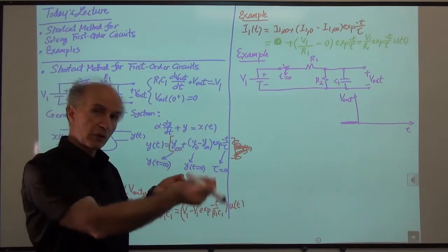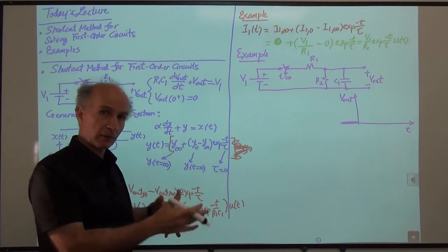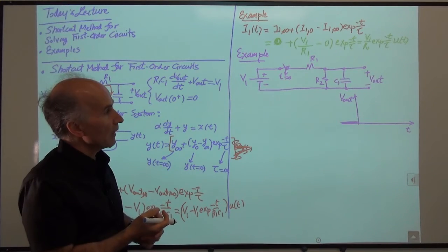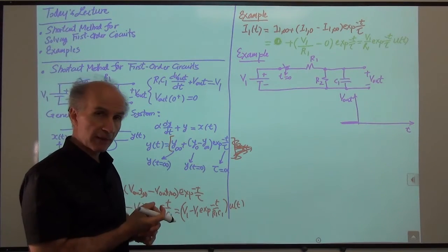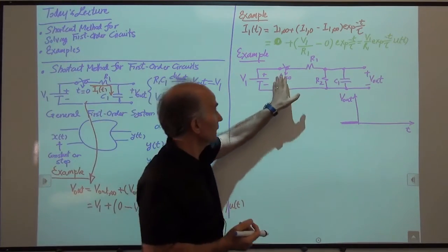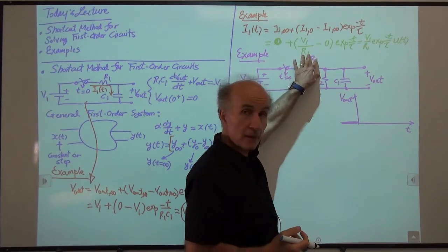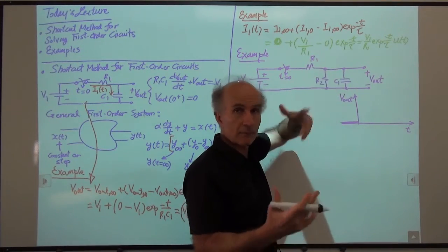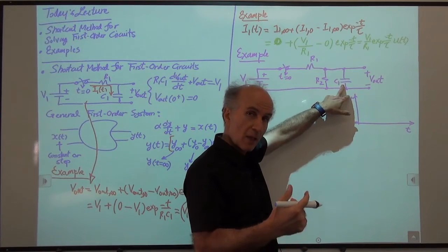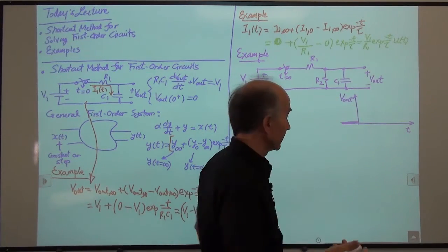At time 0, the switch turns on, and the battery begins to deliver charge to the circuit. The circuit wants to draw some current, so we'll have to see what happens. So how much is V out at time 0 plus, right after the switch closes? Well, we know that the current available here is definitely less than infinity. We have some finite voltage, some non-zero resistance, so any current that flows here has to be some finite amount. So the capacitor voltage cannot jump instantaneously. That means this voltage has to be still close to zero at 0 plus. So we are right here.